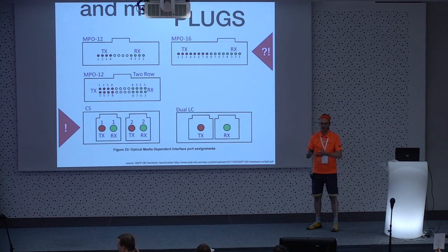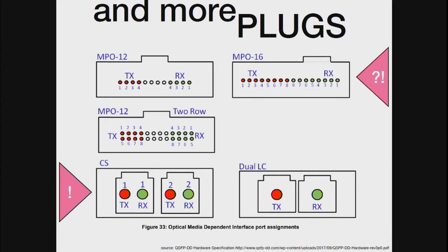Previously there were 2 fibers on an SC or LC plug, and suddenly with the MPO we had 8 fibers. Now on 400 gig technology we do have 8 lanes, and for TX and RX in total we need 16 lanes. So yes, there will be a new MPO, MPO 16, and lucky us, there is also a keying up there. The keying will avoid that we plug an MPO 16 into an MPO 12 slot, for example. On the single mode side, that's a dual LC, pretty straightforward.